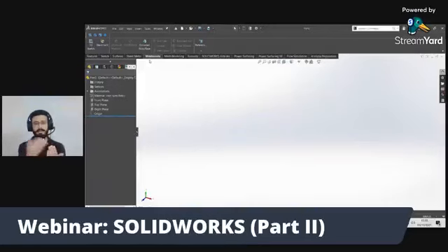And when we show this file to the fabricator, to the workshop worker, it will be easy for them to know how the design is made and how the design is working, everything. The best thing about weldments is that it contains all the standard things, like pipes, square pipes, and beams. The options given in weldments are standard ones, which exist in our market and in our workshops. These are international standard dimensions given in SolidWorks.